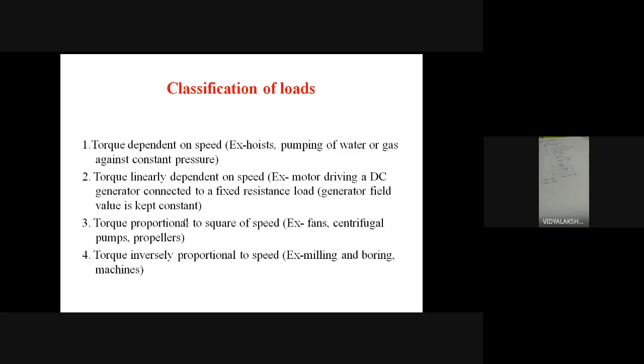What is meant by active load torque? Whenever the drive rotation is changed, the load torque retains its sign. Whatever it may undergo, it retains the original sign. That is called active load torque. But passive torque, while it is rotating, whenever opposition of motion occurs, changes its sign according to the reversal of motion. That is called passive load torque. An example for passive load torque is a cutting machine.